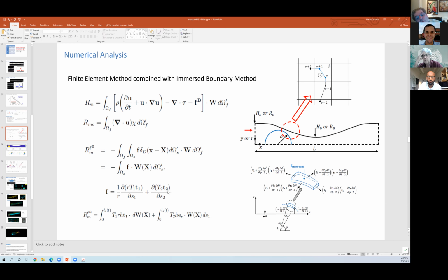That's what's equilibrating this. So at the end, in terms of the finite element model, when I have the weighted residual of the Navier-Stokes equation, I need to integrate this, but this is only acting along this line, this one-dimensional model. So the area integral of this force becomes a line integral. So whenever I have a residual that has this one-dimensional solid domain inside that element, I need to add the line integral for that weighted residual.